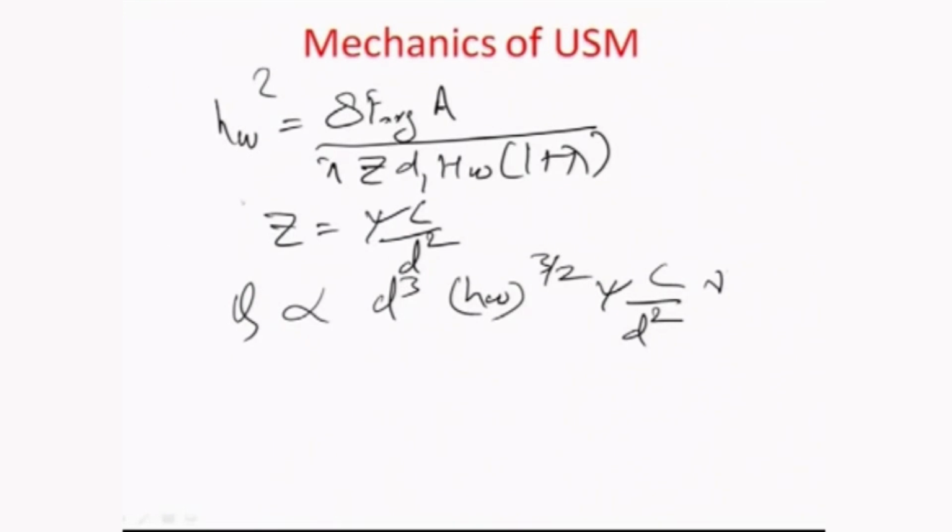One thing which is interesting to observe here is that the z value still is dependent on the average grain diameter value, for obvious reasons: the number of particles which are making impact on the surface between, let us say, a fixed tool area and a fixed working surface is really determined by the area of projection of an average overall grain, and the area of projection of an average overall grain is nothing but proportional to the square of the average diameter of the grain, not the diameter of the projection. Projections can be many on a grain surface, okay.